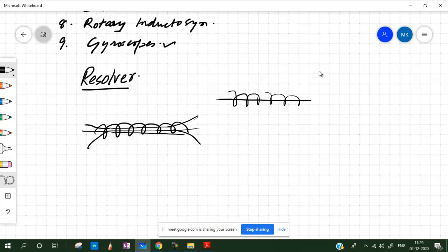Now if we place another coil near it, and have a core in between the two coils, these two coils could be concentric, they could be like this. By the principle of mutual induction, an induced EMF will be generated in this coil, and it will have a voltage or potential developed across its ends. Obviously, this depends on various factors like the core material, the winding, the turns ratio and other things. So we have something called the transformation ratio. Ideally it can be one, but generally it is not one. There are different types of losses associated with it. But this is the basic principle.